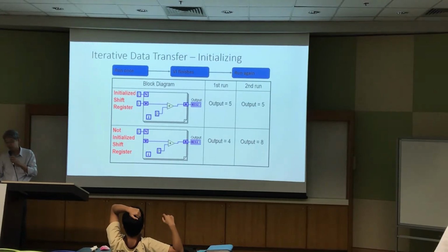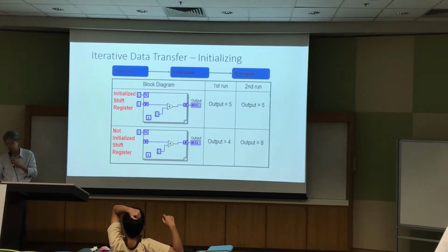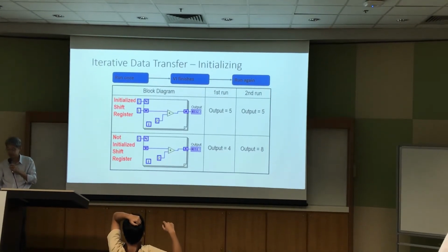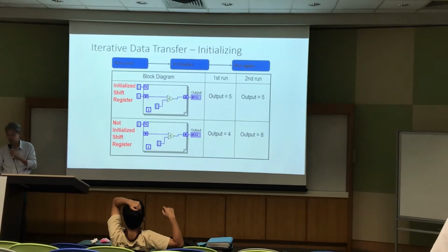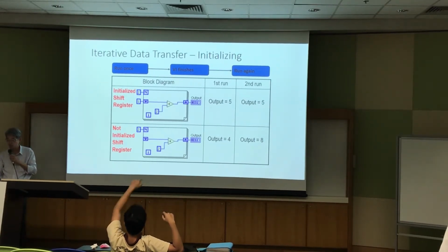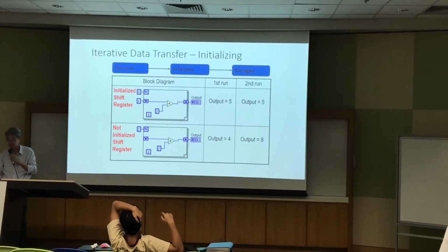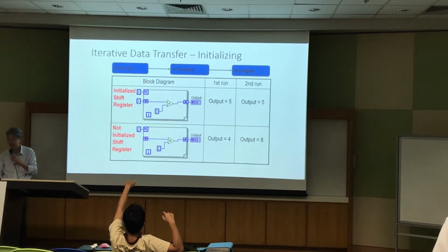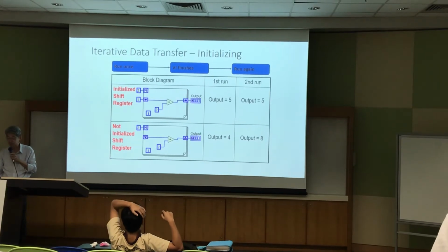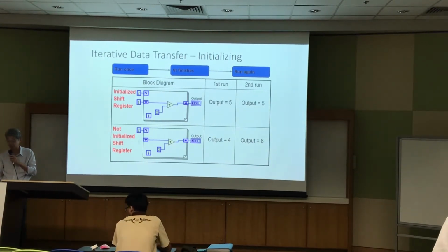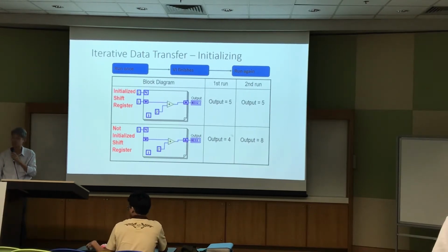And this is talking about shift registers. That is also part of the state machine. This pair of registers, I hope you remember, are basically feedback loops. These two rows of data contrast shift registers that are initialized with a 1, and shift registers in this second row that are not initialized. So this has an impact on its operation.